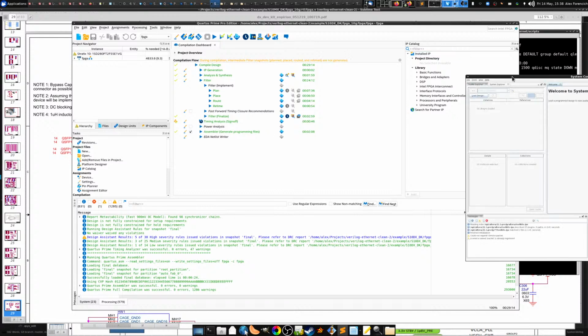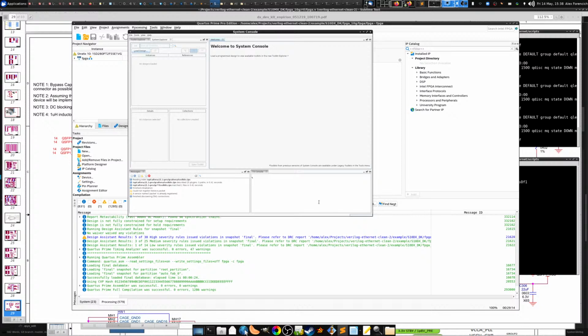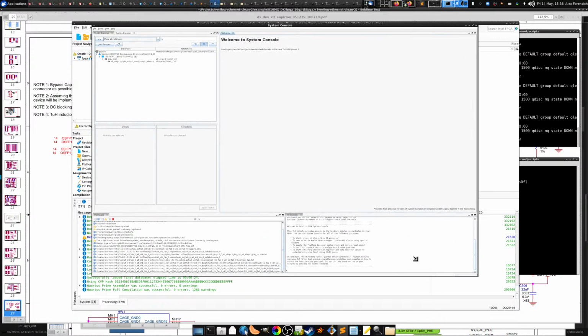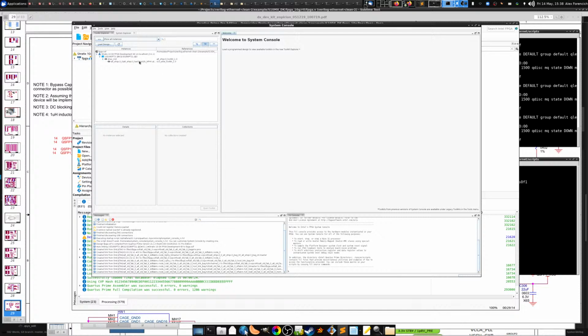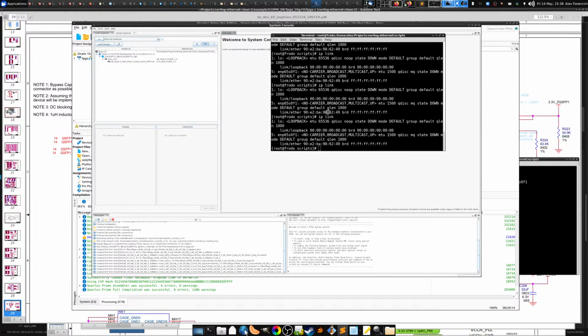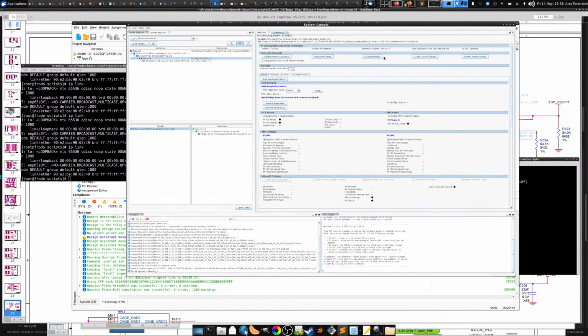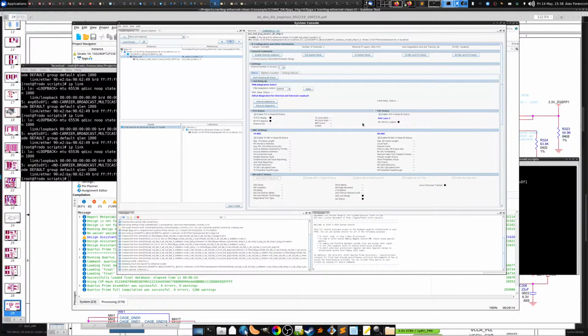This one can communicate with various debug components over the board, or over JTAG. It will take a second to start up. Using this, we can take a look at what's going on at the other end of the link, basically. All right, so what do we got? We got the MAC, and it looks like the PHYs. I'll start by opening up the MAC component, E-Tile Hard IP Toolkit. This gives you a whole bunch of stuff that you can look at here. Go ahead and start reading all statuses.